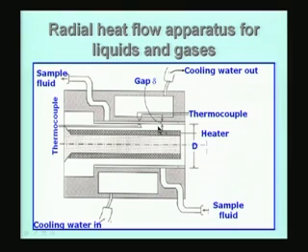The theory of this is very simple. I have a diameter d which is typically 25 millimeters or maybe a little more, maybe 40 millimeters, and the gas gap thickness is very small, sub-millimeter. Therefore, we can assume that the layer is almost like a planar layer, because the area change from inside to outside is so insignificant. If delta is very small compared to capital D, we can assume that the gap is just like a planar layer as far as heat transfer by conduction is concerned. So, I put a thermocouple inside and a thermocouple outside. This thermocouple pair is going to measure the temperature difference across the gap between the inner cylinder and outer cylinder.